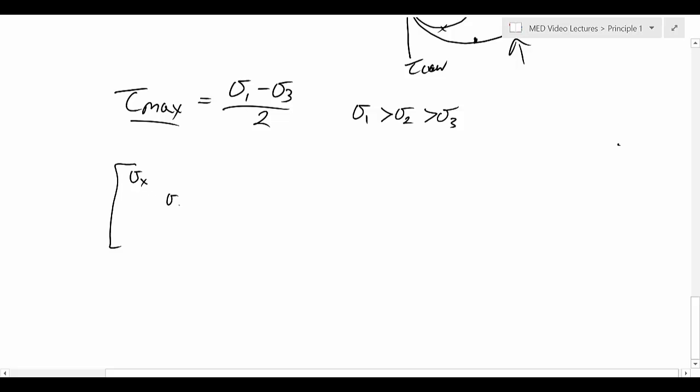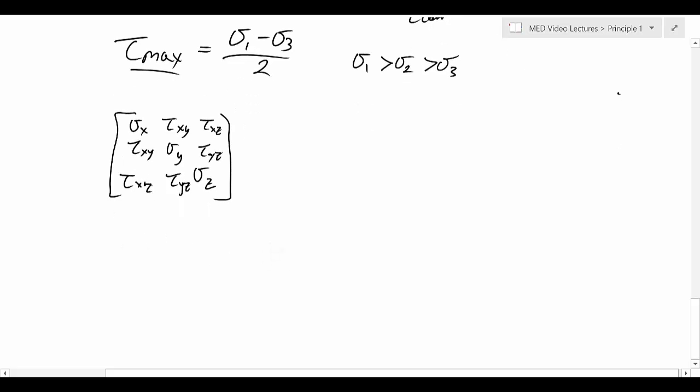So if we have that situation where there is stress on the outside surface, say a pressure vessel is a great example, it's possible that we may need to find all 6 values of the stress states. So recall that those two values are the same. So there's a couple different ways we could go about doing it. I suggest using eigenvectors, the eigenvalues.